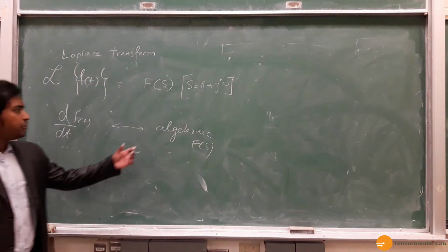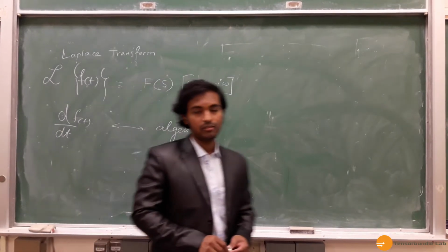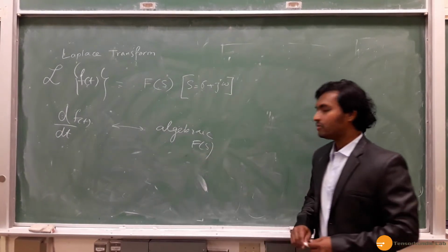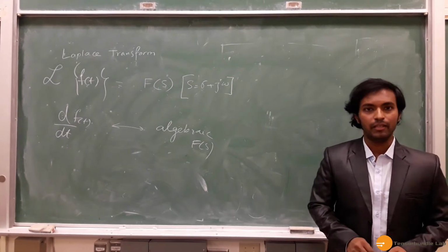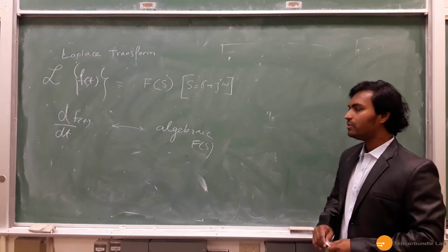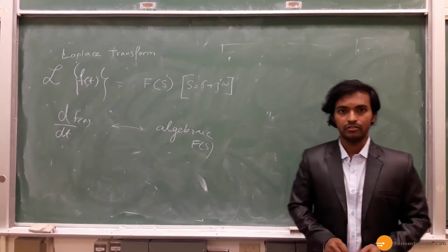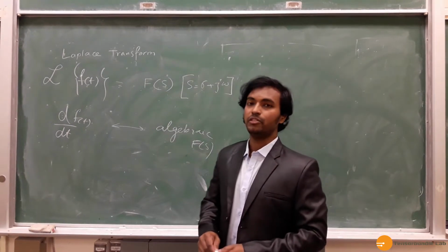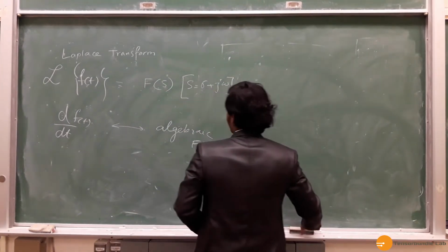So it's much easier to deal with algebraic equations compared to differential equations, and we can solve the algebraic equations and find out the transfer functions from simple mathematical manipulations. But in the time domain we have to use some complicated methods to solve the differential equations. So that's one of the greatest advantages of using Laplace transform in circuit analysis.